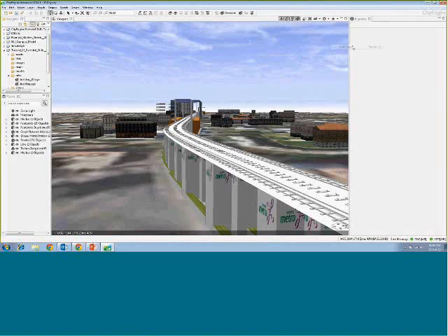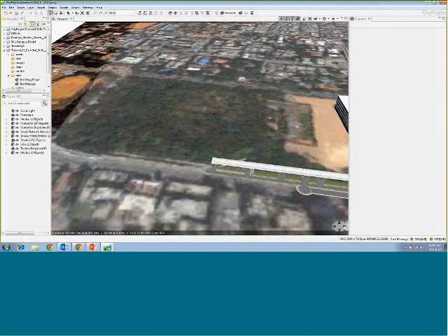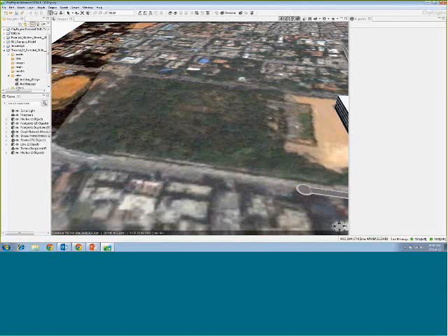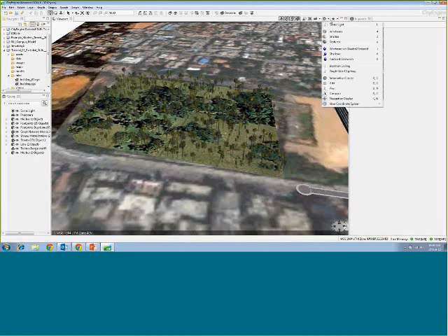Now take for example this particular landscape. If I apply some landscape applications on top of these buildings, it aligns itself and creates a 3D model. You may control your scene light parameters and visualize your models accordingly. So going ahead, CityEngine would not only model your buildings and streets, we have also rules created for various trees and more natural environments.